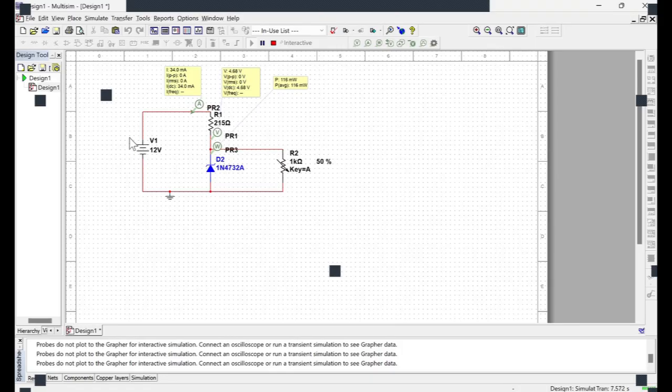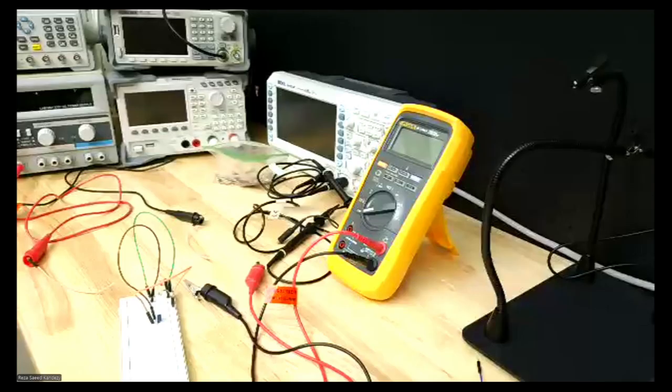So whatever happens in the source or the load, if the Zener diode falls between the minimum current and maximum current, it would keep the voltage stable. That is the expectation that we had based on our calculation, and you see that this happens in the simulation too. Now let's go toward the actual experiment in the lab.